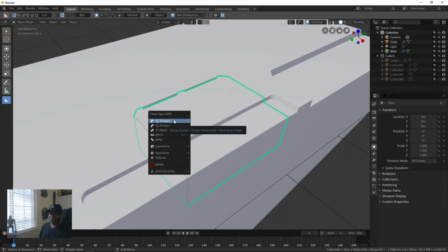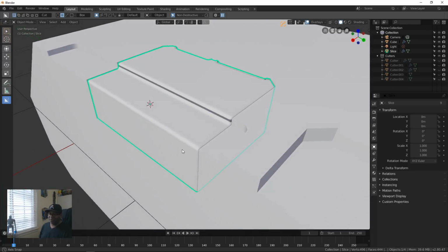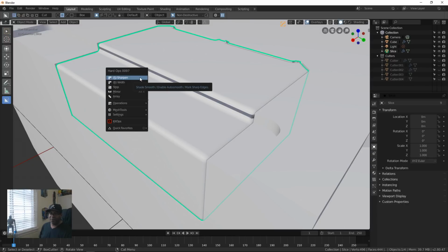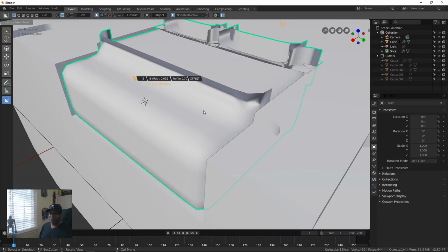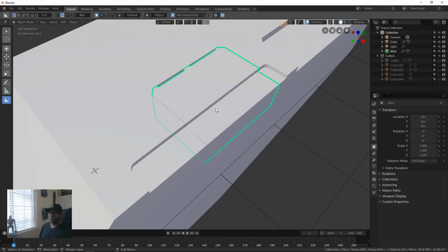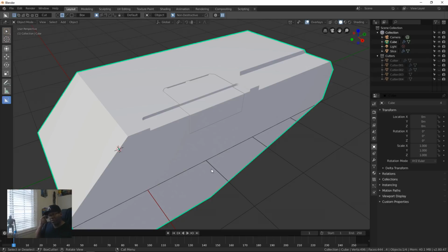right, the other mode by hitting Q, if you have both installed, I'm going to do a C sharpen, which actually puts a bevel modifier on the edges of these things, right? And you can see it's spaced here because the bevel is set pretty wide, but if I hit Q again, and then B, and then apply a B width, basically just scrolling back and forth, I can make this a nice rounded edge, like it's been filed or polished, and then it won't be absolutely sharp, because a lot of times, hard surface stuff is kind of interesting when you're working in 3D.